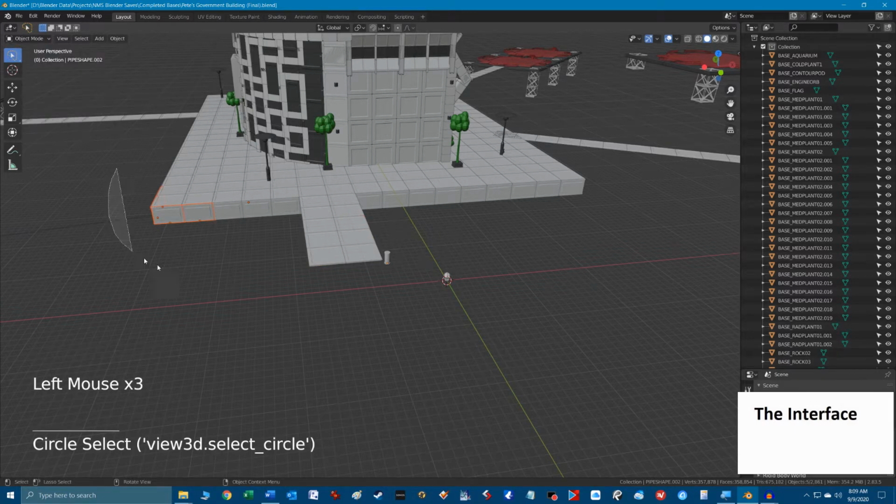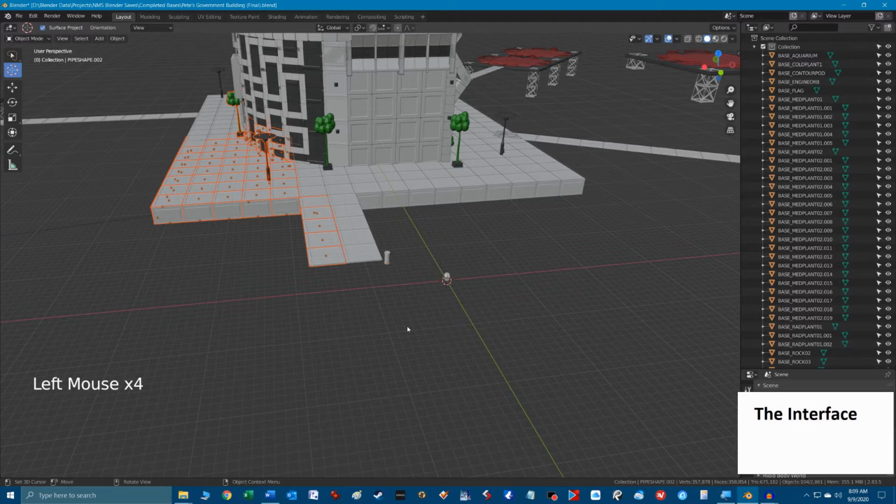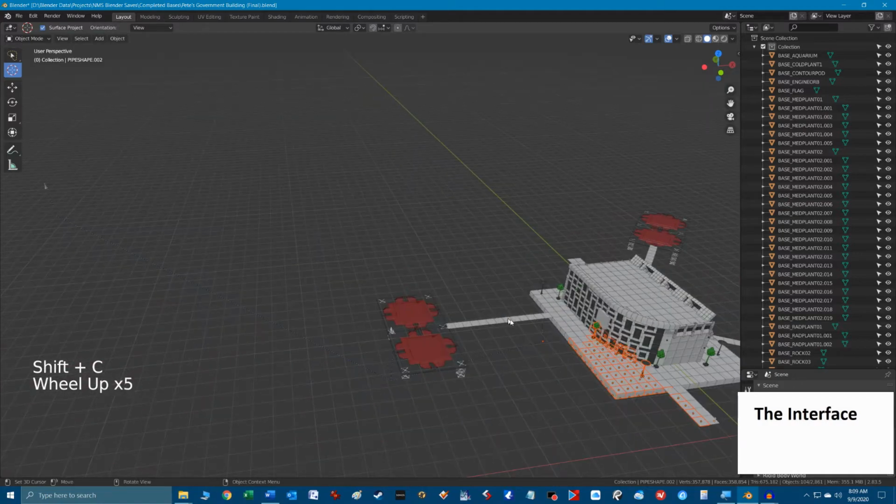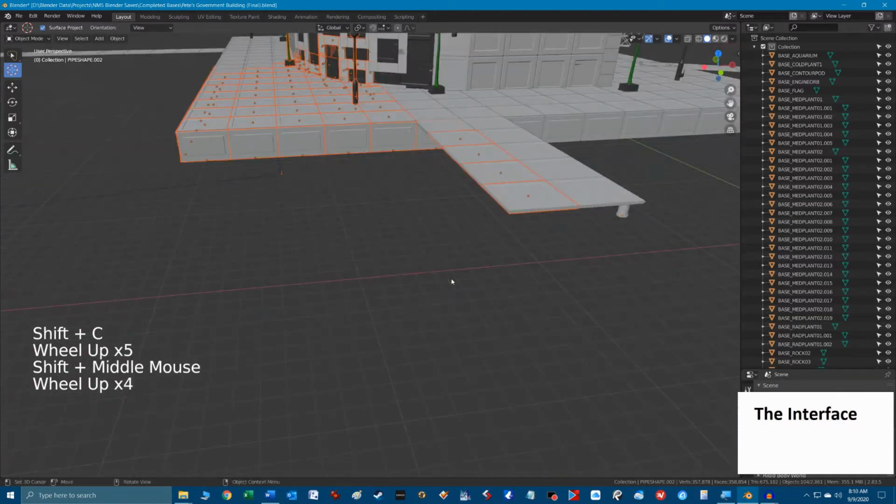Next tool is a 3D positioning cursor. You can click on the 3D workspace to position this cursor anywhere in the workspace. We'll get into using this cursor for some advanced stuff later on, but you can think of the cursor as a place marker that you can do some cool things with, like rotate objects around it and snap objects to it, etc. Also, if you want to position the cursor back to home at the base computer at 0, 0, 0, hit Shift plus C, which also puts your whole base into view in the 3D viewport.